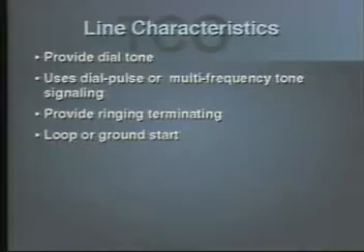How the telephone company starts. I'm sure several of us have picked up the telephone and dialed someone and actually heard them lift their receiver and talk before we heard their phone ring. That's because we had a collision of the calls in the network, and what we heard was a facsimile of their phone ringing. We didn't actually hear their phone ringing. Many of us may have even picked up the telephone to make a call and found someone already on the line. It's a little unnerving, but it can happen, and that depends upon the kind of electronic connection that we have. And that's what we refer to as a loop or a ground start.